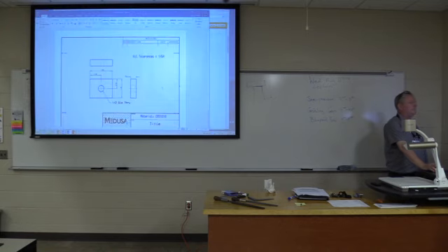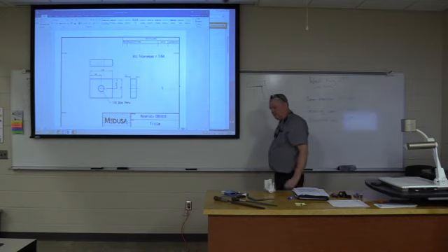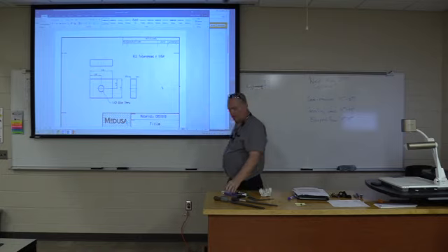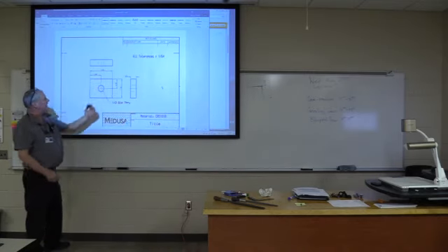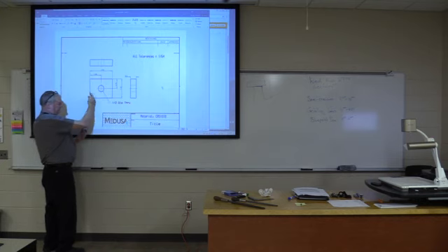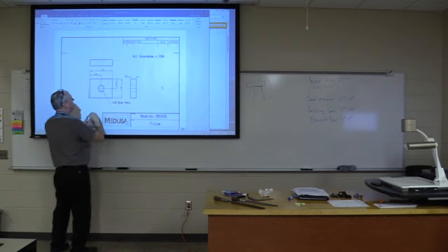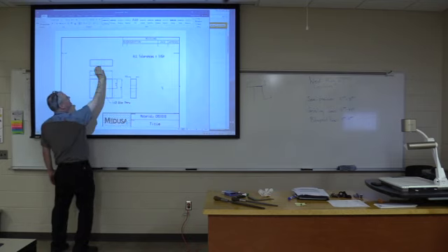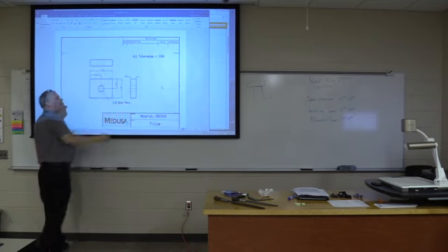I realize some of you might not be able to read blueprints just yet. But what this is showing us is the block we just machined. Here's the length of it. This is that 2-inch length. This is the height, 1.5 inch. And then this is our thickness. So you look at the part like this, and then it comes out of the screen like that, and it comes up like that. This is what we'll talk about a little later today in blueprint reading.